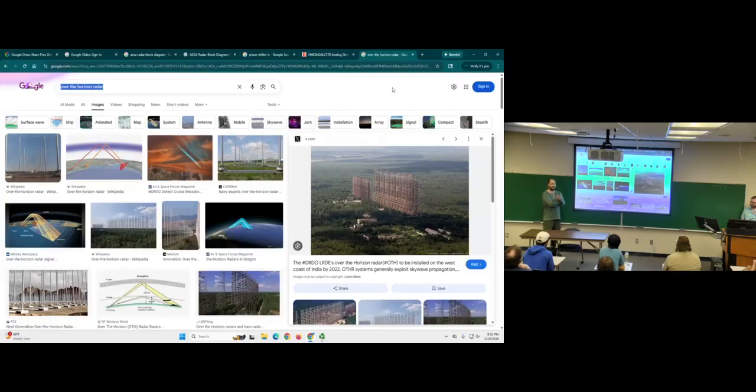If you guys were to make the project we mentioned, make a tracker and purchase a radar, you're not gonna get a phased array one. So any radar you do make, you're gonna have to gimbal the thing. But those radars for commercial use and so-called automotive use, because a lot of self-driving cars and other cars just have those sensors in them now, those are actually far higher frequency, probably 27 gigahertz, 72 gigahertz, 92 gigahertz. Texas Instruments sells radar chips at those frequencies for like $5. Full radars just on a chip. They're very impressive. So you can actually do quite a lot.